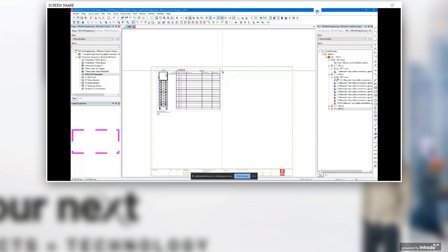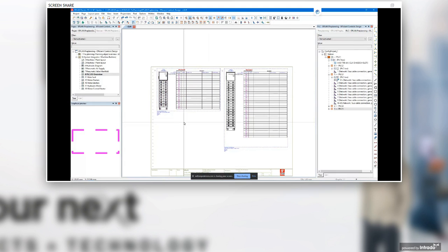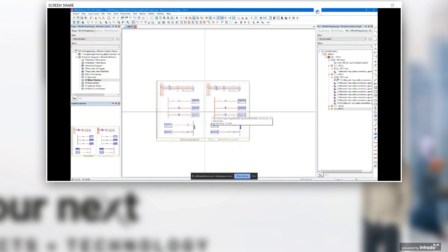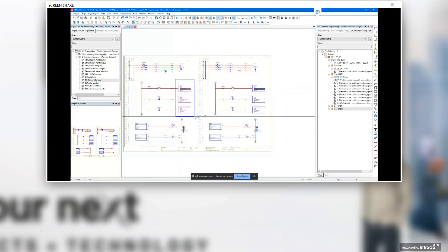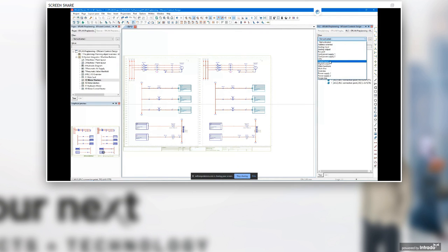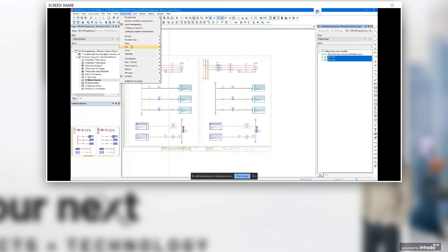Now that I've got my cards imported from the configuration, I'd like to map these I/O points from my card to the I/O points available in my design. So I can do it different ways. I can either highlight them here in the drawing, or I can select them in this navigator view. So I'm going to change the view to look at all my I/Os. I'm going to filter by inputs, so digital inputs, and then I'm going to select these 2 inputs, and I'm going to go to assign my PLC use in my connection block wire.